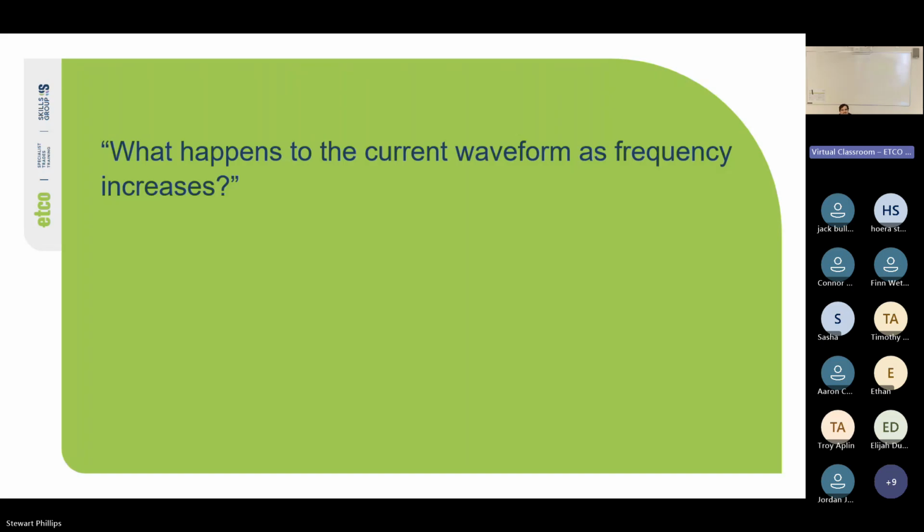Yeah, well, not more resistance. Remember, resistance is the reference line, and our inductance is the upright. So the hypotenuse is going to get longer, which is the representation of impedance. So if our impedance is increasing, what's going to happen to our overall current level?